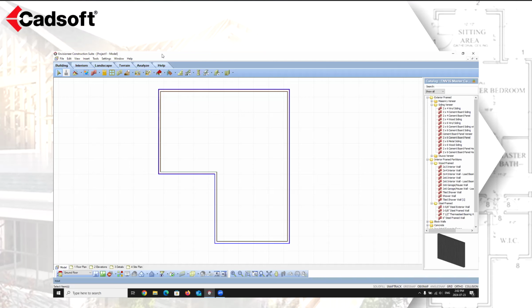Most builders do not frame in this way. Instead, they create a floor frame that spans from one exterior wall to the other. To create this type of floor framing layout in Envisioneer, you can create a structural floor and use its various insertion options, either by perimeter, by room, or by picking points to insert floor sections that more closely resemble those that will be built on site.